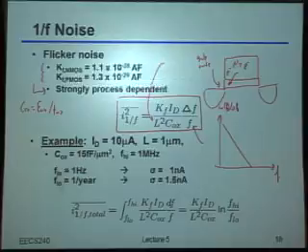Are you increasing the total drain current? So by the way, notice I've fixed the drain current here, right? I'm externally biasing the device. So for a fixed external drain current, if I increase the channel length, what's going to happen to the sort of device? Lower the resistance? Well, and by the way, I'm talking about the MOSFET channel length. I'm not talking about a normal resistor here.